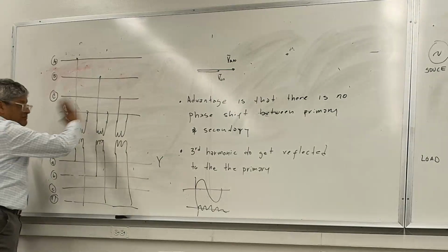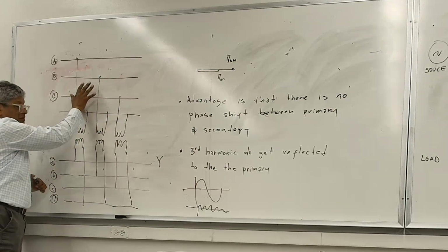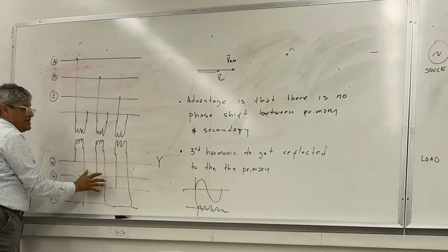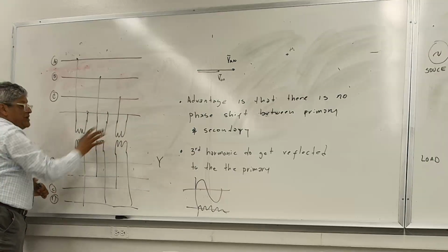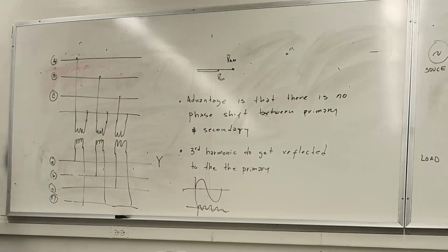But as I said, I'm getting too much into the details. The important thing is that you can take 3 single-phase transformers and connect them any way you want. You can make it Y, you can make it delta Y, you can make it Y delta, or if the transformer is designed from the get-go, sometimes they just design it as you specify.